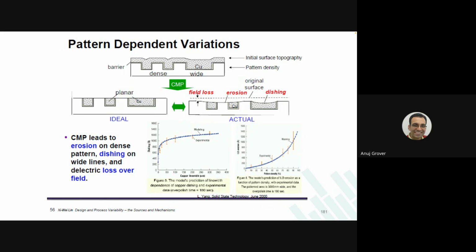Now, what does this do? This increases the resistance of those wires and it reduces their capacitance, at least sidewall capacitance reduces. If you are designing something to model another wire, you have to ensure that even the density of wires is similar across the two regions. So a replica bit line could be thousands of microns away from the real bit line that you want to track, but you still have to maintain the same metal 2 density when you are modeling the bit line.